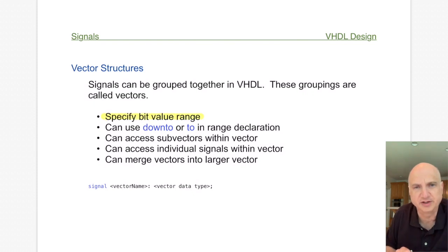So that means you can specifically name individual bits, or number them actually. You can number individual bits inside a vector by specifying a range. Typically in most digital design, you would number your bits with the highest number on the left, and the far right bit would be bit 0. So you typically start ordinal 0. You start with 0 on the right and work your way up. This is just the standard way of representing binary values throughout all of your digital background, right?